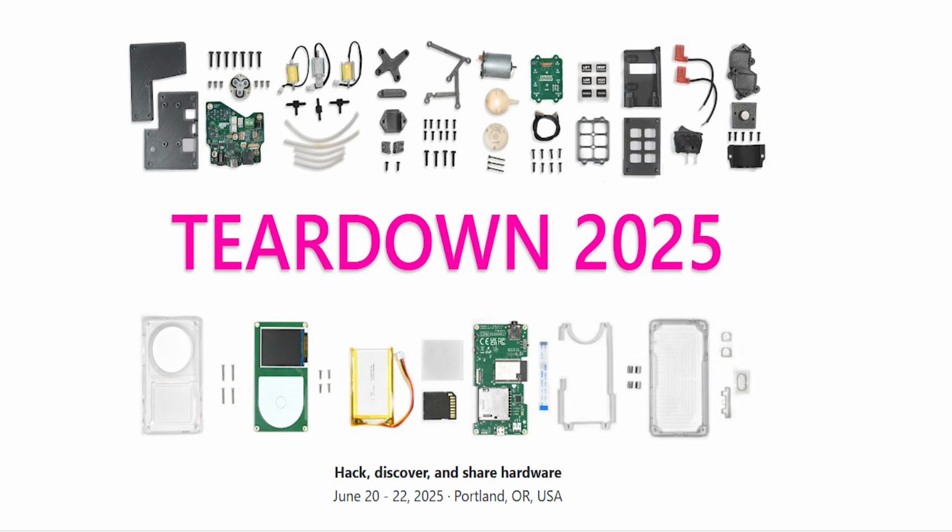What controls that ignition coil? So now when I'm looking inside the software, I know that anything to do with output compare 1 is driving the ignition coil.